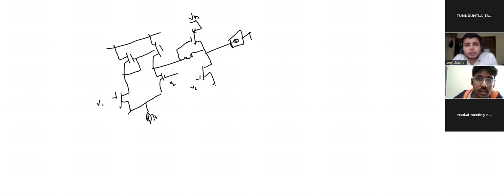Why did you use this common drain then? Just to make the output resistance zero, sir, because if we use only these two stages, the output resistance will be higher. Just for the idea, we implemented a common drain. So you were not driving any load, you just put the common drain here to minimize the output impedance. Yes. The project idea is to design only till here, sir. This one we just tried, like the ideal op-amp parameters we studied earlier: output impedance should be zero and all. Just to understand that, we tried.